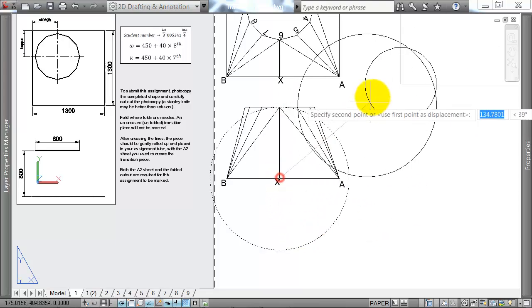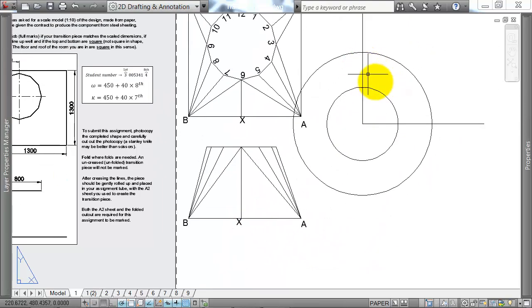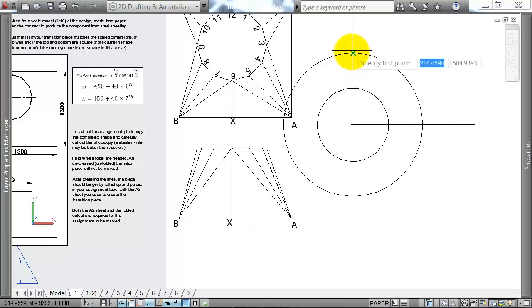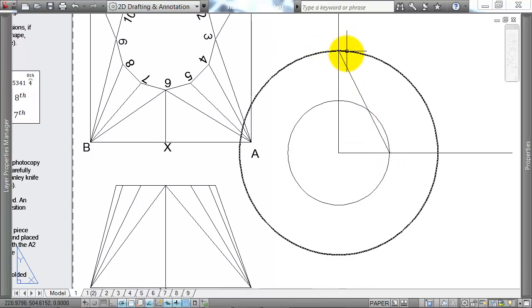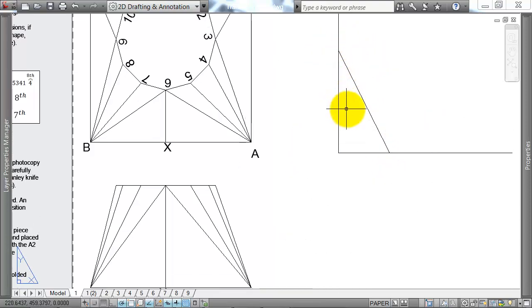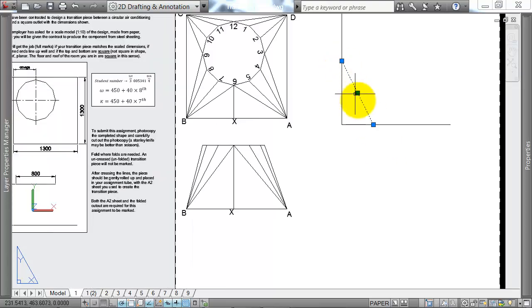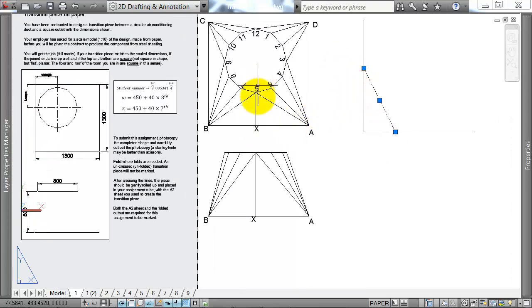Move this mark, get my compass information over to here. Now, if I draw a line between the intersections of my two compass marks, you wouldn't draw a full circle, you just draw a small little mark down here. Between my compass mark down here and my compass mark up there, what I find, this line here is the true length of line x6.